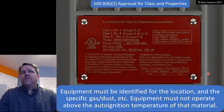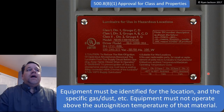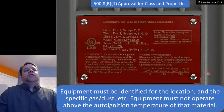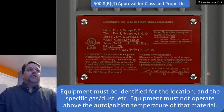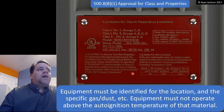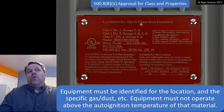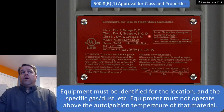B1, approval for class and properties. Equipment has to be identified for the location and the specific gas or dust, etc. And the equipment must not operate above the auto-ignition temperature of that material. All right, so here we have a piece of equipment. It's a luminaire. It's listed for use in Class 1 Division 1, but only in groups C or D. Again, it's not enough to know that I'm in a Class 1 Division 1 location. I need to know the group.